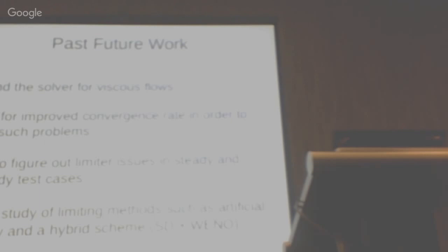In the Euler case that I've shown here, the shock typically stays in the same cell, or the marker for the limiter stays in relatively the same position. However, when you add the viscous effects, I would not expect that. I would expect it to transition or to move along the iterations. But it seems to me that when you have a shock wave, then the number of iterations grows. So basically, you don't have a scale of it. So yeah, that's a much larger can of worms.